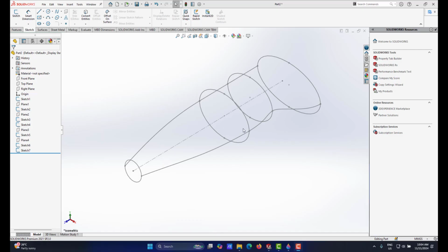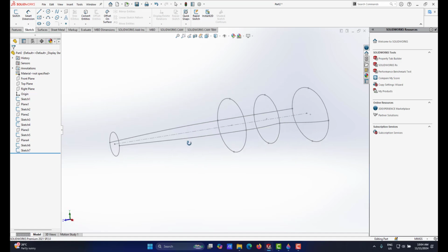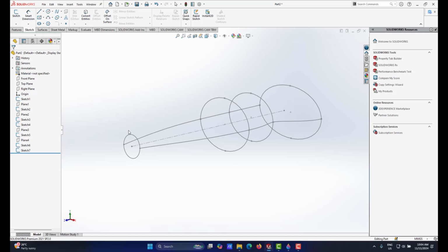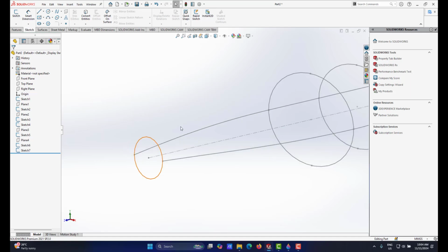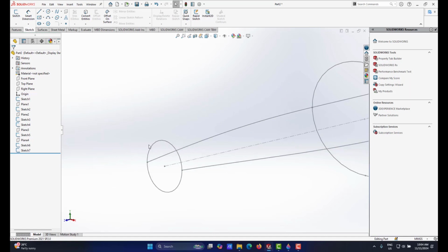All right, my next move is that I have to create another guided rail. If you look at this level, I have to make a guided rail that will pass through this quadrant point of the circle, and also it will touch that quadrant of that circle. I mean, the guided rail will pass this quadrant point of these three ellipses, and also it will snap at that quadrant of the circle.